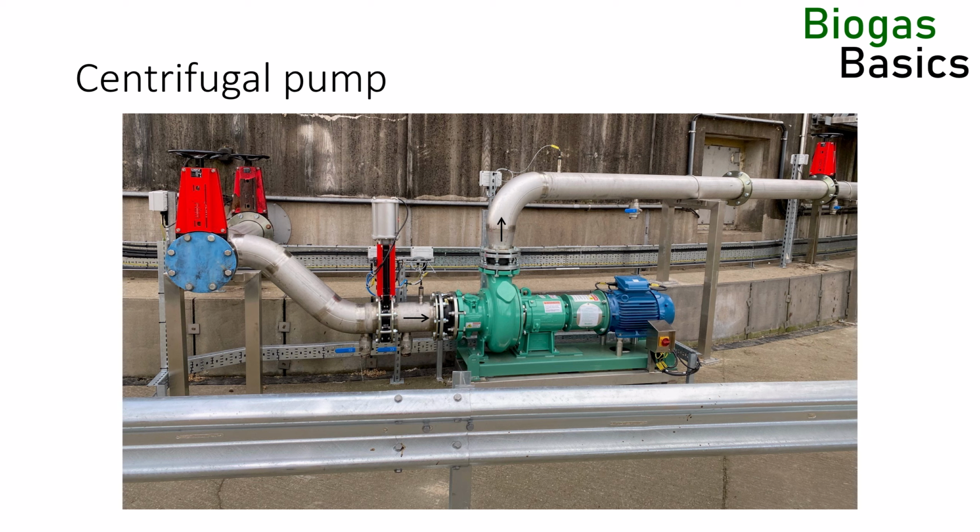One special property in biogas applications is that centrifugal pumps can fill with biogas when they pump digestate with entrained biogas bubbles. Digestate is supersaturated with dissolved CO2, and the high shear forces in the centrifugal pump will transport dissolved gases to the gas phase and coalesce gas bubbles. The lighter biogas can accumulate in the eye of the impeller, blocking the center inlet while the heavier liquid rotates around the circumference of the body where the outlet is located. This can reduce the volume flow of the pump and gaslock the pump.